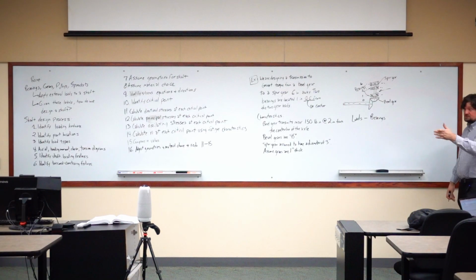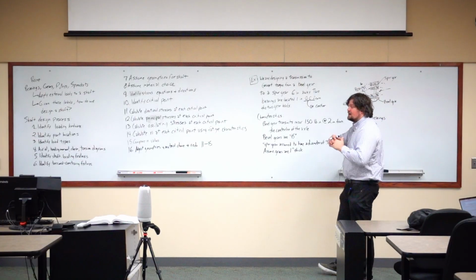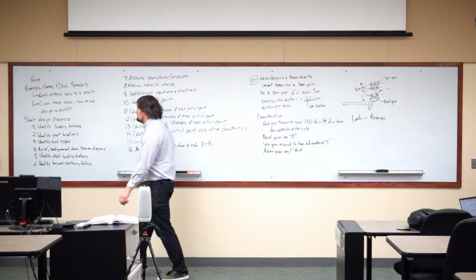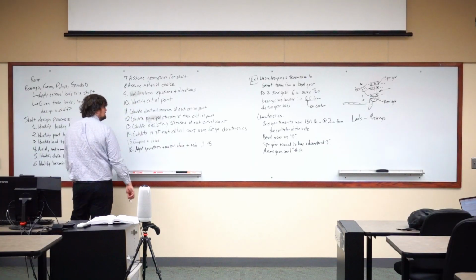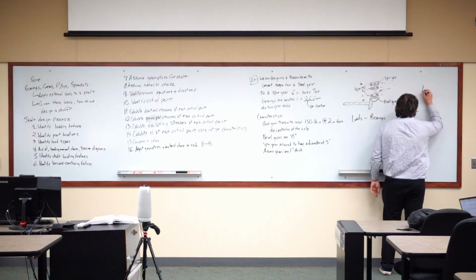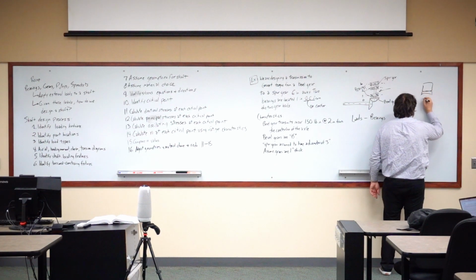The shear forces do oppose the bending moment, but likely they don't provide any kind of constraint in any of these axes. Oftentimes the way that these bearings are designed is that it will be some kind of housing, and then on the inside you'll have some kind of a bushing or something, and usually that bushing has the ability to swivel a little bit.